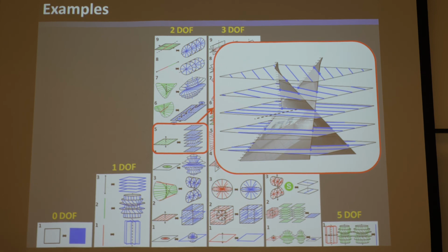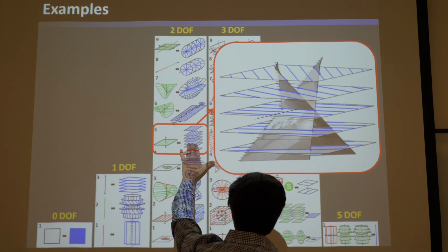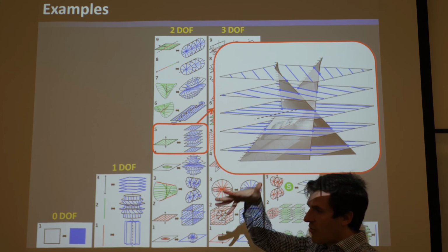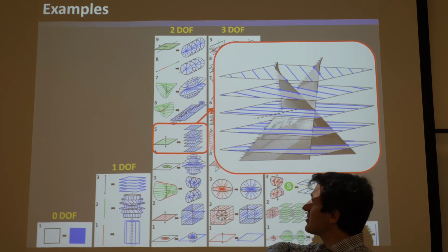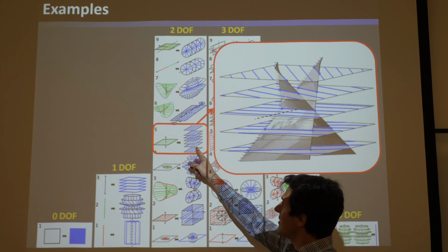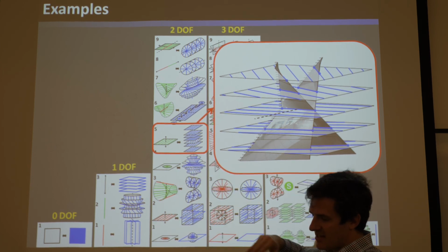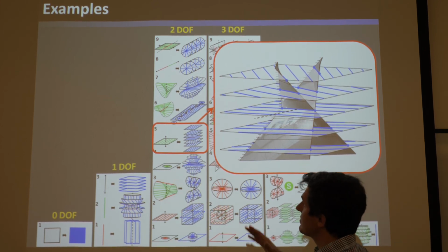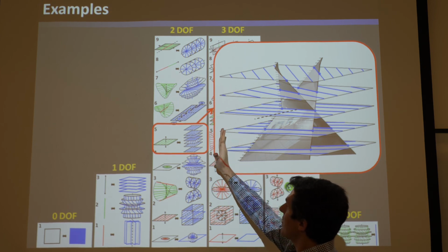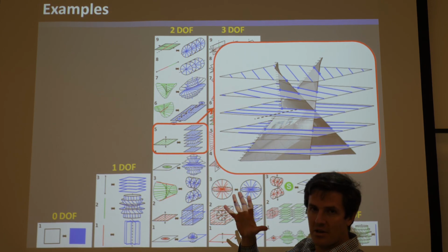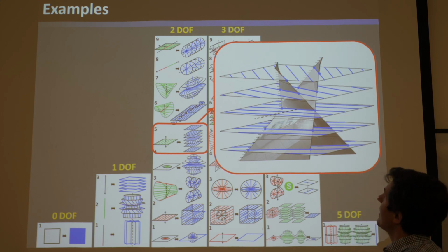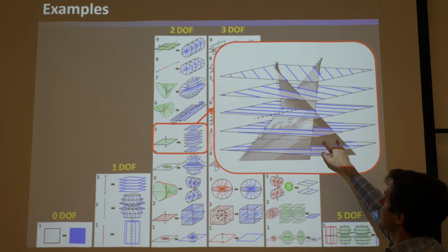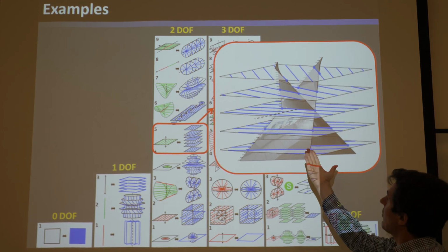These are constraint spaces you're not entirely familiar with, but this is a bunch of stacked parallel planes of parallel blue lines where the blue lines rotate at a very specific pitch. Another way to think of it is that the amount they rotate as they translate is the same as hyperbolic paraboloids, as the blue line rotates and translates through those. So you could think of these as a bunch of hyperbolic paraboloids stacked next to each other, like Pringle chips are stacked, right?